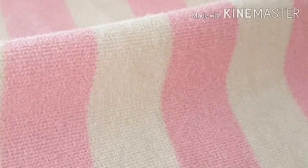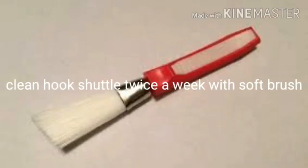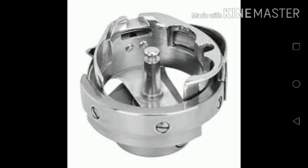The next description is of the hook shuttle, which is a part of the machine. It has been scheduled twice a week with a soft brush, and its remarks include removing the dust and threads, and cleaning the feed dog, trimming mechanism, hook set areas, feed bar areas, etc. This all comes in the third category.